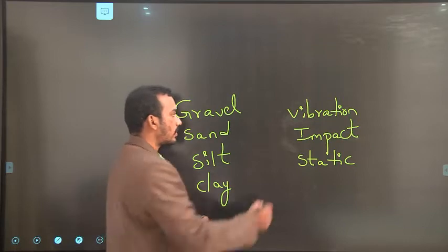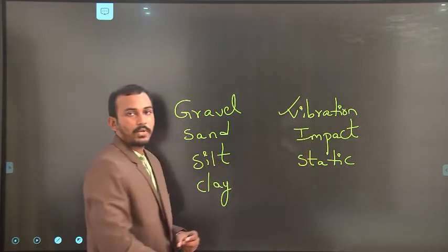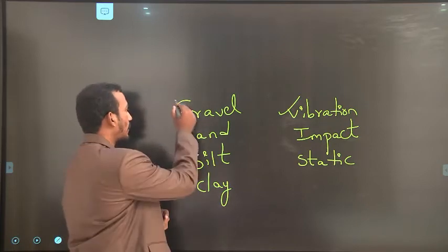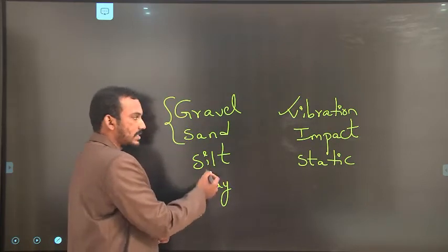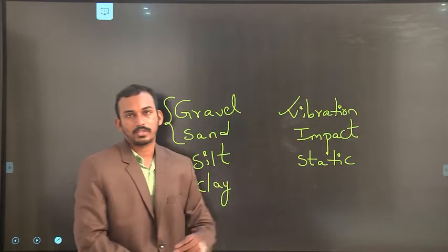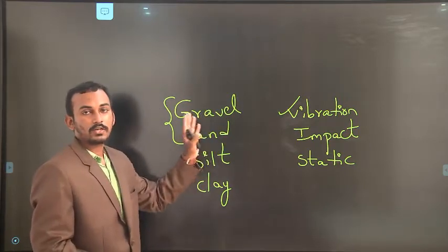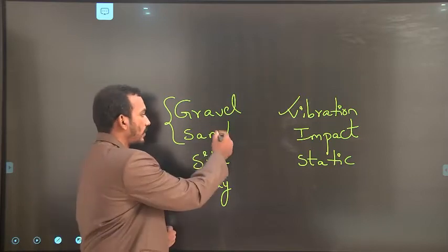The first one is vibration force. By using the vibrations, we can only densify the granular soils. We cannot densify silt and clay using vibrations, right? So, in situ densification of granular soils. These 2 are coming under granular soils.